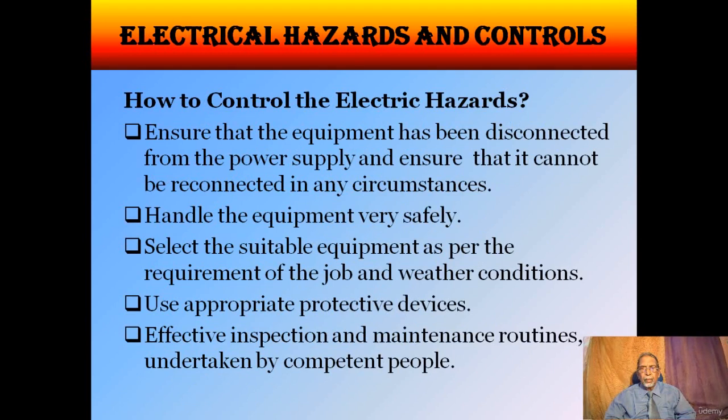Now we will see how to control electrical hazards. Ensure that the equipment has been disconnected. First you will have to see that all the equipment is disconnected from the power supply and ensure that it can't be reconnected in any circumstances. Then handle the equipment very safely.